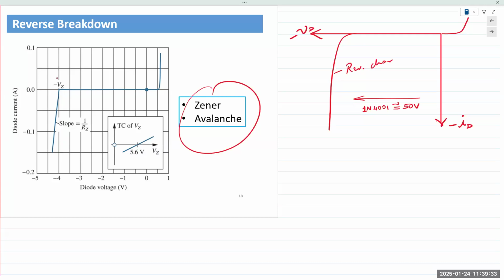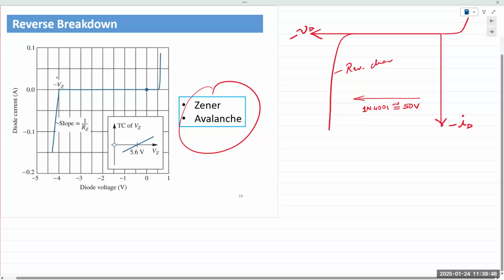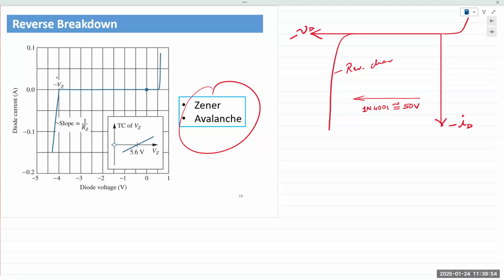There are already existing charge carriers present around the depletion region, and in reverse bias the electrons in the covalent bonds acquire enough energy from the external electric field that they are able to break free of their bonds and start crossing the junction.